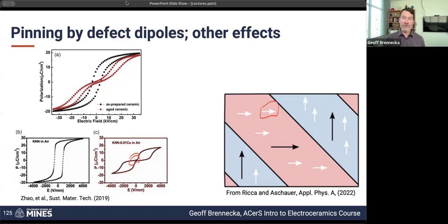We're actually going to cover anti-ferroelectricity next week. But in this case, that response is not because of a true anti-ferroelectric structural setup. It is because of a bunch of very highly pinned domain walls. And the reason that it finally switches is that you get to a high enough field that you can actually drive these ionic defects to hop and move around, and get real diffusion of at least a couple of lattice parameters.